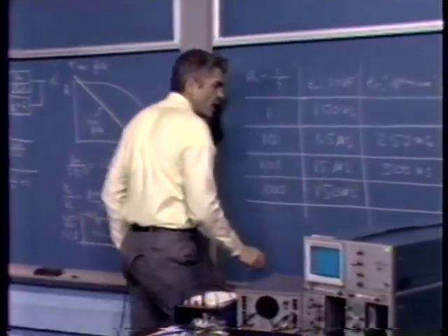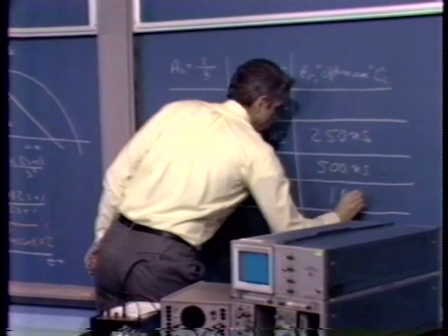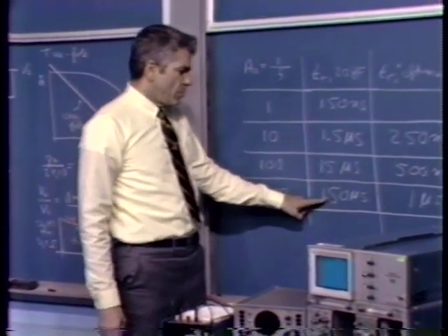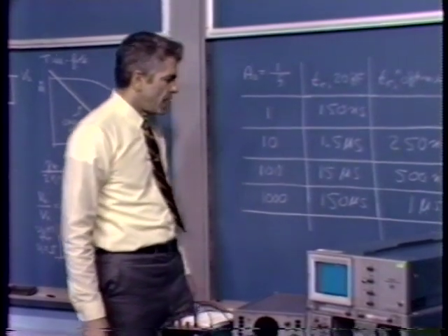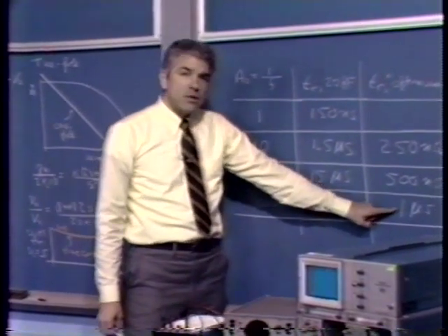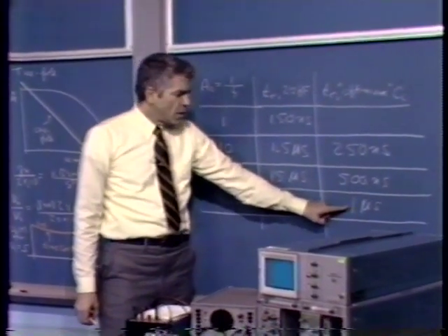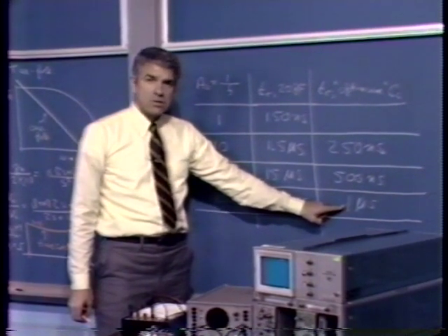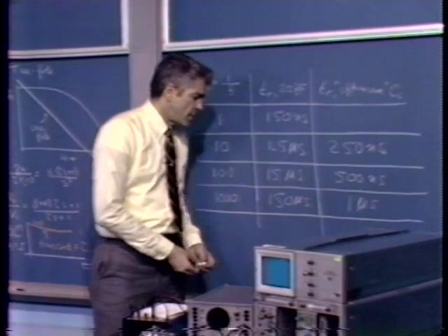So we get about a 1 microsecond rise time, roughly a factor of 150 to 1 improvement in rise time and correspondingly bandwidth. When we compensate with this small value of capacitor, we still have something like a 350 kilohertz closed-loop bandwidth at a gain of 1,000.